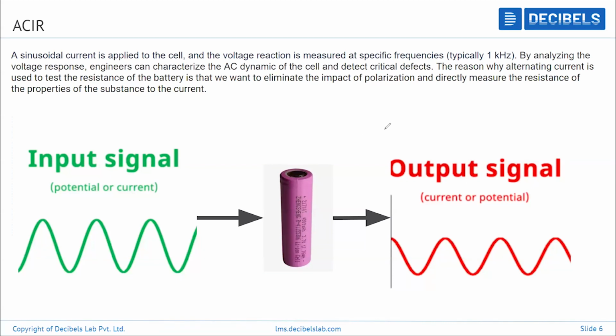Here, EIS sweep is nothing but measuring the impedance at different frequencies by applying the AC current at the different frequencies. What could be the frequency range, and in what frequency ranges what all things can be captured, we can discuss in the further part of the session.